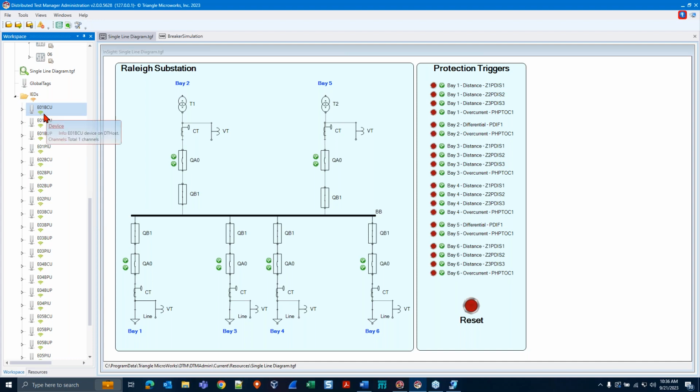Conveniently, you can tell where the IED exists and what its function is based on its name. That's of course because we named it so over in Helix. E was the name of our voltage level, which everything exists in. 01 denotes the bay. BCU refers to a bay control unit, where BPU would be a bay protection, backup protection, and process interface unit. And this is the IED that interfaces directly with the physical breaker, opening and closing it.